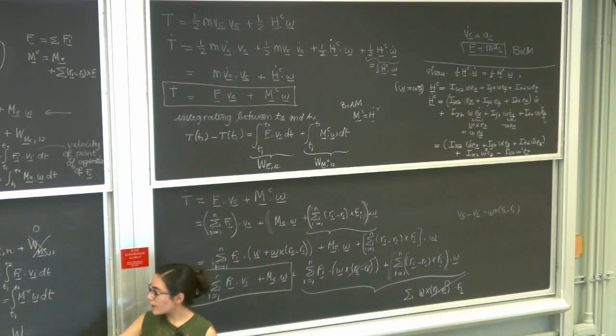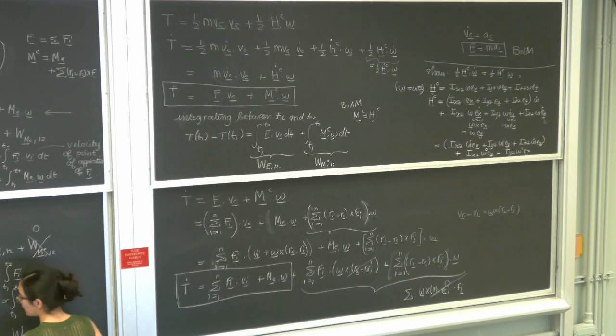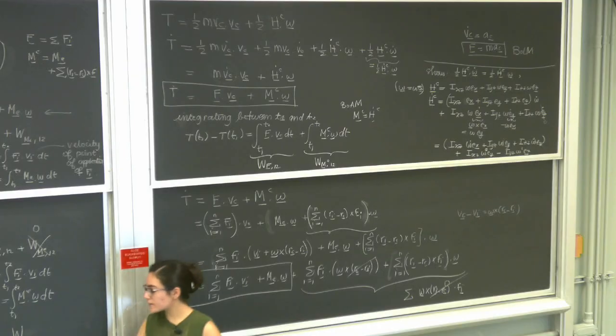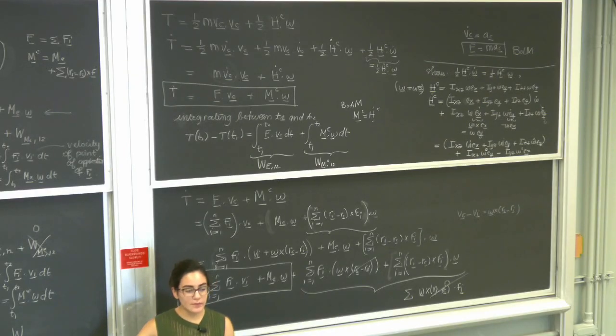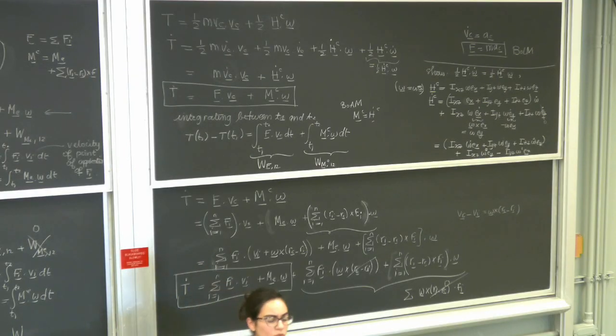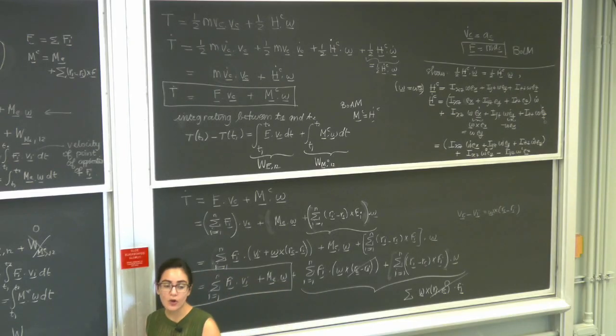The weight is a conservative force. We can write this work as a change in potential energies. It's going to be mg (h2 minus h1). H is the height of which point? The center of mass, exactly, the point of application of the weight. Now, what about the work of the reaction force at O?